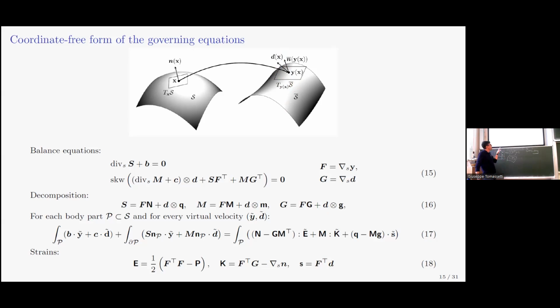So as you can see, when you go from 3D to 2D, you have to add additional dynamical quantities, bending moments, and additional kinematics. But what is interesting here is that I do not postulate this measure of bending. You find a lot of papers in the literature where people assume that the bending energy depends on this tensor, and then they develop their calculations.